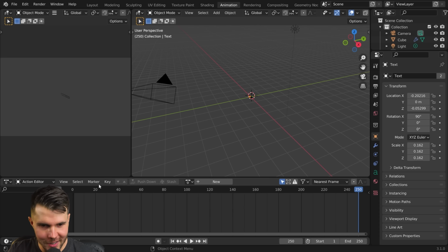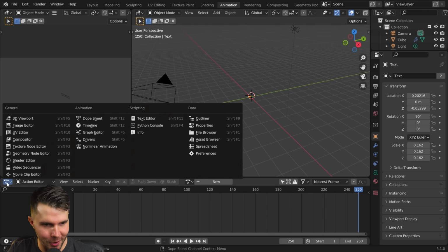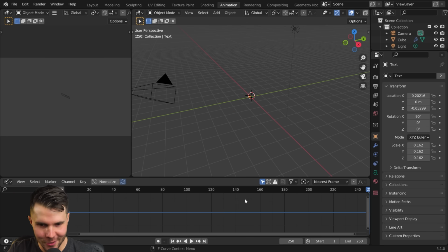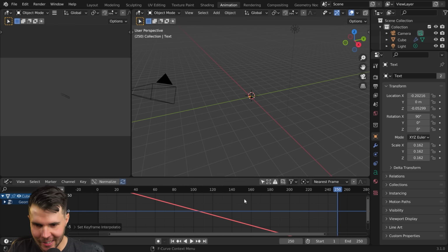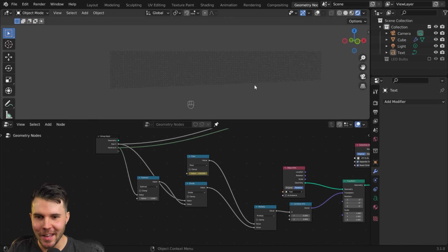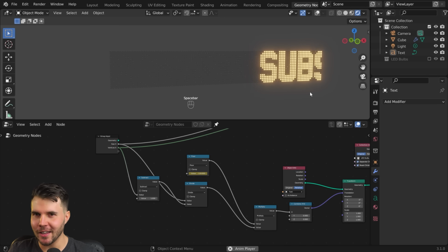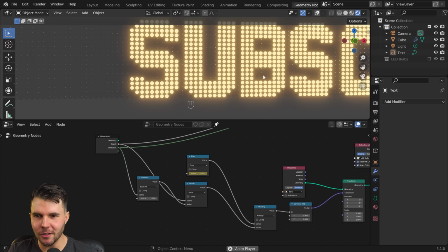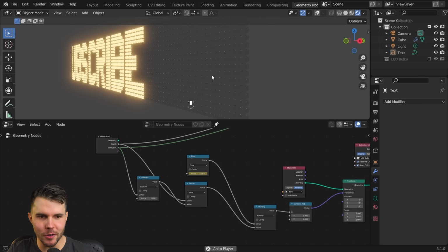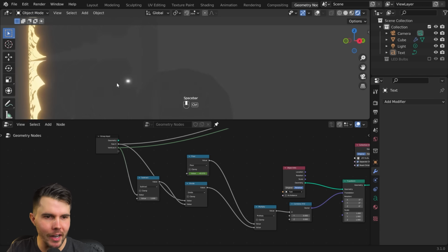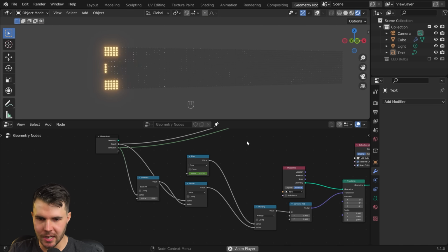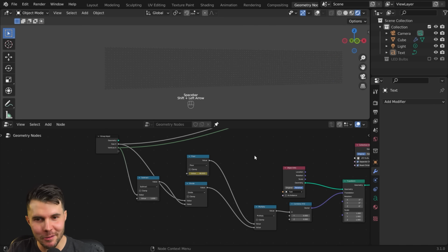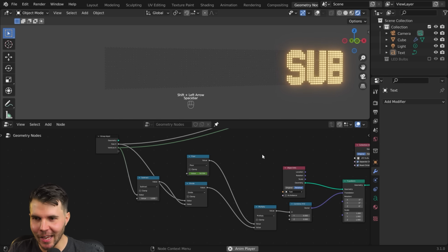And then because Blender always creates a Bezier animation, let's go to the Graph editor. I just want to do it quickly, just as a demonstration. Linear, there we go. And now if we play this back, we should see a perfect, no jittering, beautiful looking LED board that you can even get right up close to and see the bulbs, and it just works, which is cool. But it could be even better. Believe it or not, it could be better.